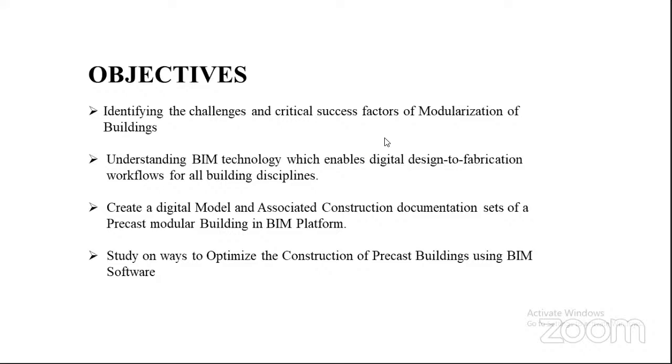Decisions can be taken on the panel knowing its status, and the key of the whole precast concrete process is delivering the information needed to the production and ensuring that no further change will happen to the elements that have been sent to production, in order not to change the mold or rework the same element. So all these decisions prior to precasting are done in the design stage itself.